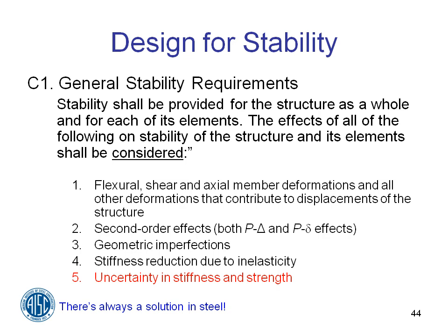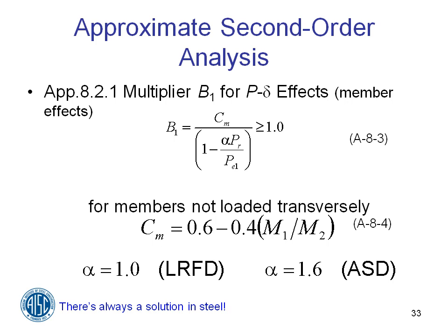Before we move on, there's a question back on slide 33. Could you clarify, are M1 and M2 due to gravity only? Yes. Well, if you've assumed that your no translation load is your gravity only load combination, then M1 and M2 are the no translation moments. So if we've assumed that gravity is our no translation, then yes, they are gravity only. Back to 44, right? Right.